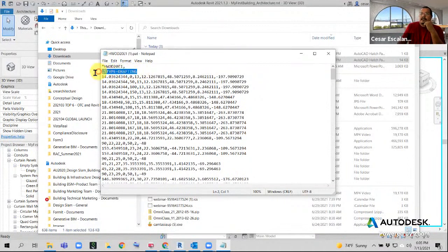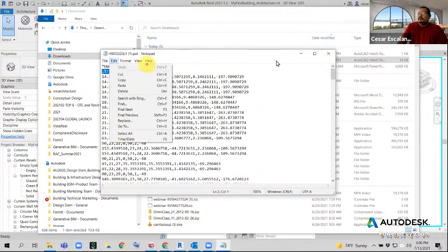Right after that line, there's a new line with the characters semicolon, percentage, type equal drafting. This makes sure that the proportion of the hatch remains fixed regardless of the view scale. That's the purpose of the drafting view. So I added this line right below the name and then saved it. Just file, save.